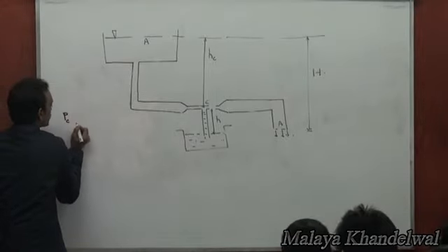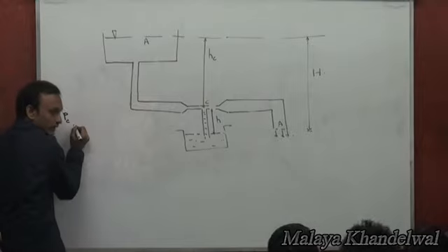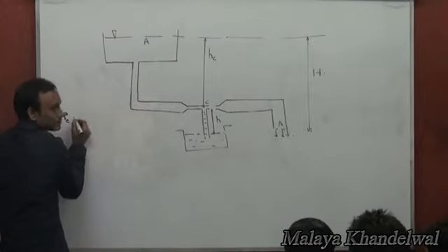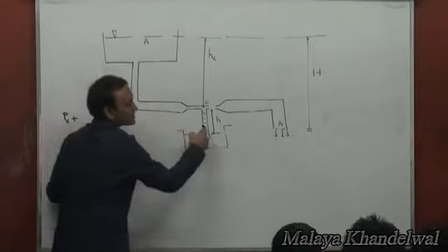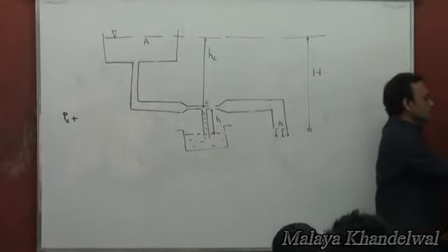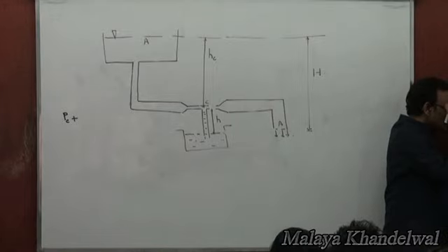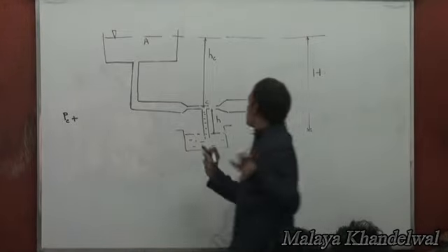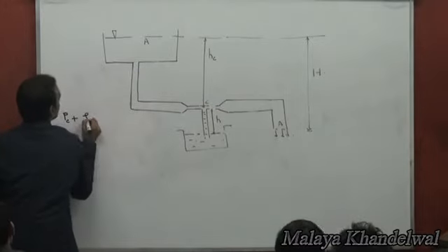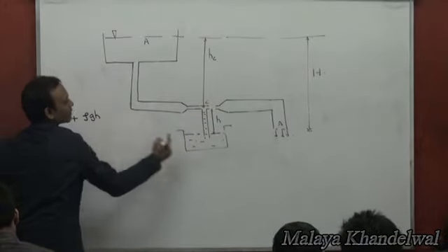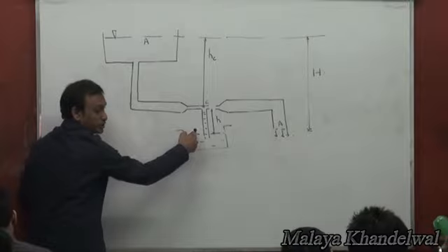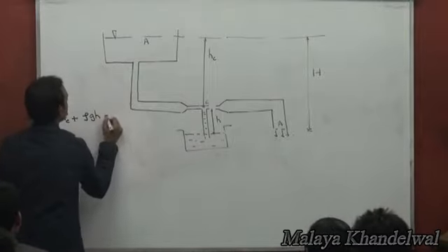The pressure at C so that it could just rise by an amount is like Pc plus rho g h of this liquid. Is it the same liquid? The same liquid. So Pc plus rho g h. That's the pressure. It could be atmospheric pressure, P naught.